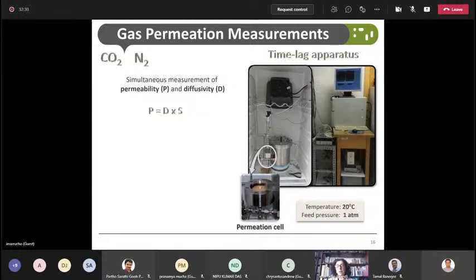To separate liquids, we typically use membranes with different pore sizes so that the solutes do not all pass through the pores at the same time. However, gases have very similar diameters, and it is very difficult to have a porous membrane for gas separation. In terms of polymers, I would say it's still not possible. So our membranes are dense.